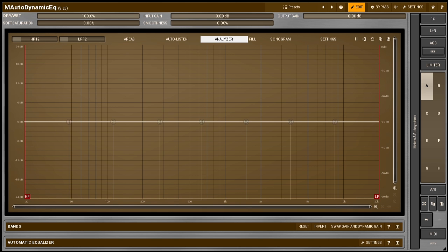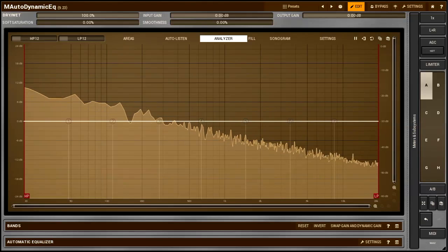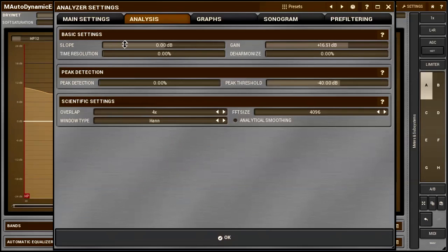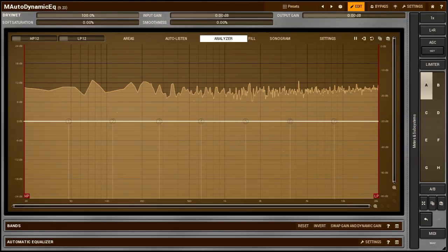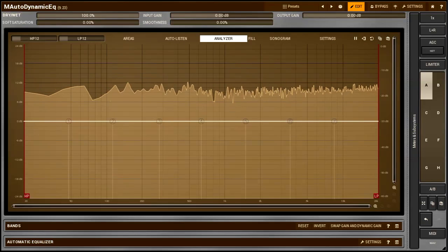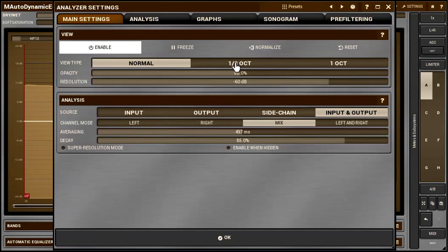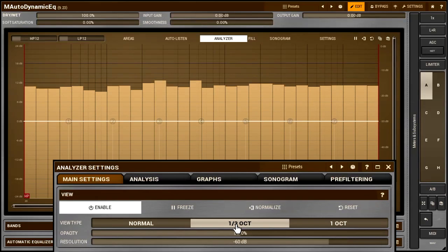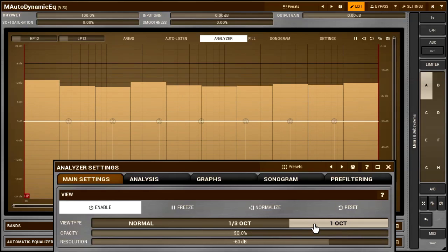Now, back to the FFT analyzer. If we play back the pink noise, the analyzer will show it as a falling line. We can make it horizontal by setting the slope to +3 decibels, and thus emulate the behavior of the analog analyzer. Moreover, you must put a +3 decibel value here if you use the 1/3 or 1 octave view type we discussed before. It's also a useful feature to judge relative amplitudes between harmonics.